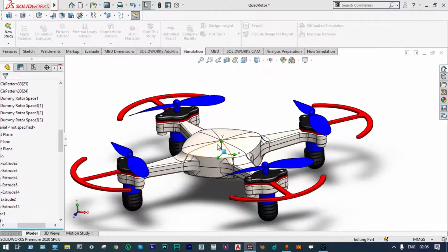In this analysis, we'll find out a lot of things like the pressure difference, which is responsible for the upward movement of this quad rotor. At the same time, we'll see velocity at different places, and also we'll select some goals, that is the force exerted by these different propellers. This force exerted by the propellers is creating up thrust. In this case, we are providing rotation of these propellers in 2 different directions. One pair will be rotating clockwise and the other pair anti-clockwise. This is done to balance the counter effects of torque or rotational effects, right?